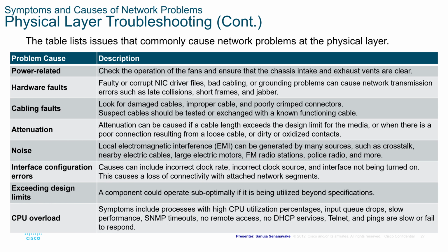But also if you put too many or certain types of Cat5e, Cat6 cables together in a bundle, and then you tighten them up or you make loops out of those, sometimes because you have a long cable that has some extra length and you decided to create a loop, right, just to keep it tight, that loop can create an electromagnetic field causing noise.